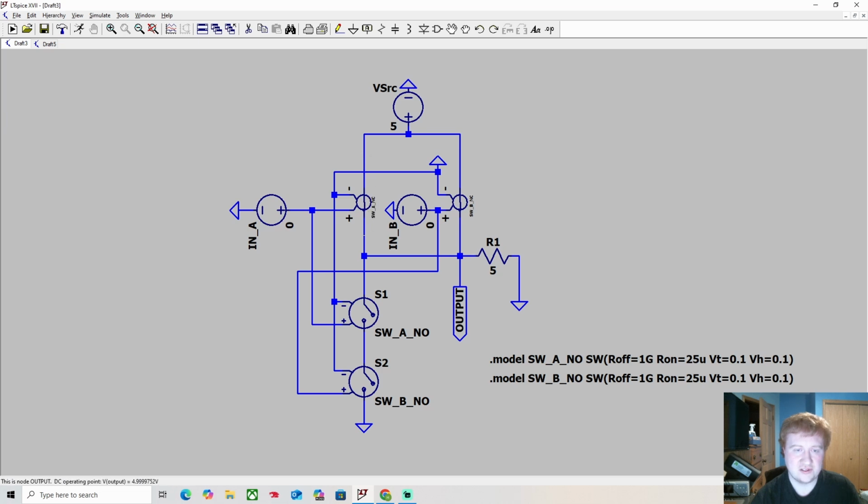We're going to have 5 volts on this side. And 0 volts also goes to this switch, meaning this stays open. So there's no voltage that wants to come through this part because this switch is still open. So nothing wants to go this way towards this ground. So there's only one way it can go. It's through the switch, through this node, and then through the resistor.